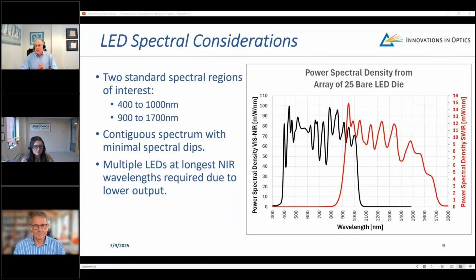So the systems we were describing have either thermoelectric coolers, which can hold the temperature to within fractions of degrees C, or liquid cooling systems, which can hold the temperature quite close, on the order of a degree as well. So that keeps the wavelengths from shifting around, and also reducing the temperature increases the lifetime of the system.